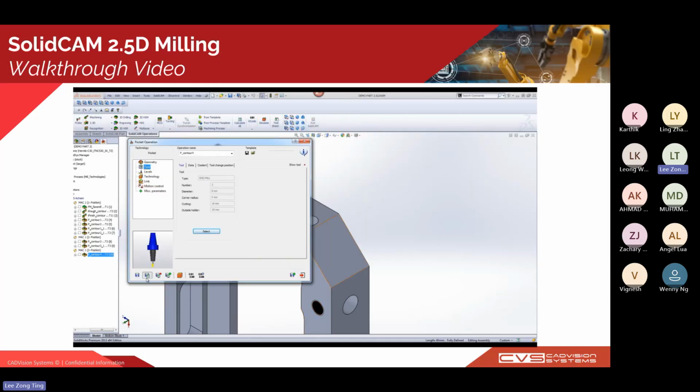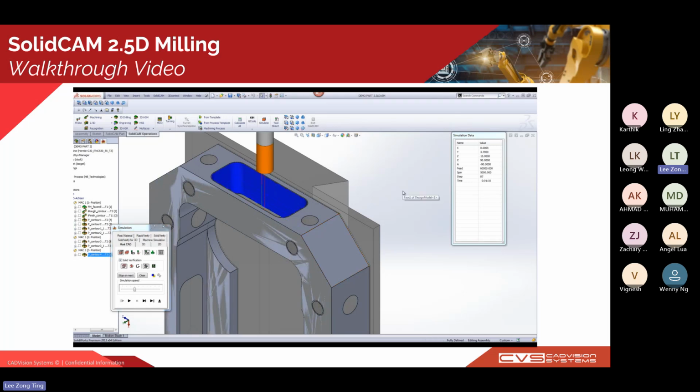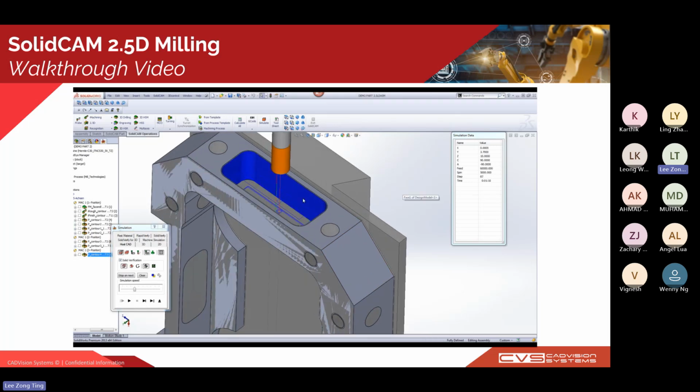Later on, you can see after we calculate the toolpath and simulate it, the end mill will go directly in the middle. But this is not what we wanted. So what people typically do is pre-drill a hole in the middle for the end mill to enter and then pocket from the pre-drilled hole.